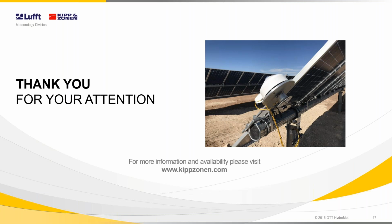Do you want to capture all the irradiance there is? Then the pyranometer is the good way to go. If you want to have a matched irradiance measurement, then you would choose a PV reference device. And yeah, it depends on which approach you take to the measurement system.